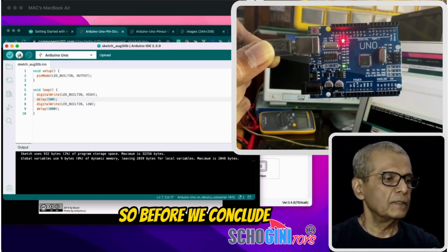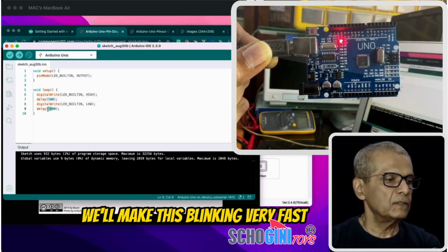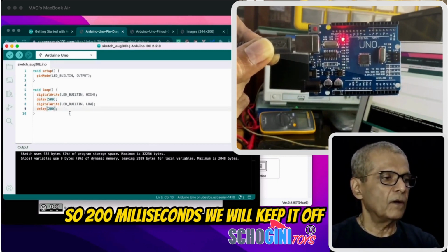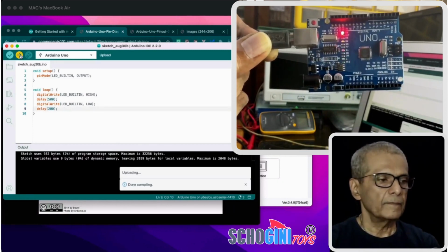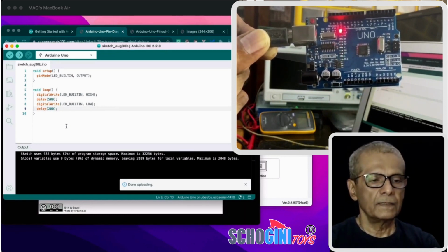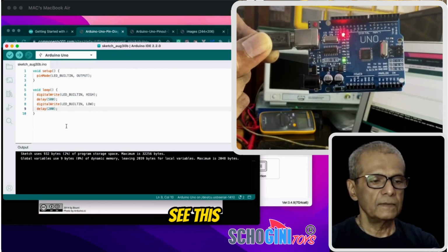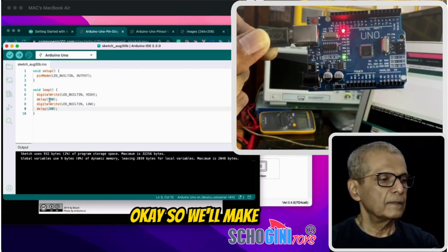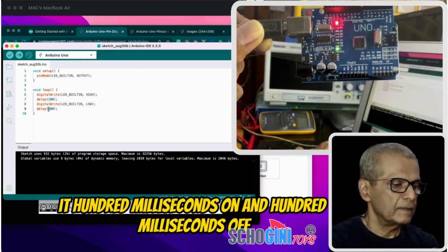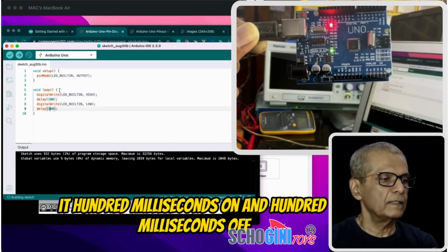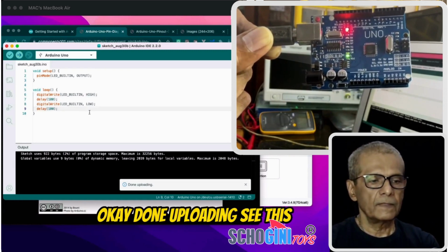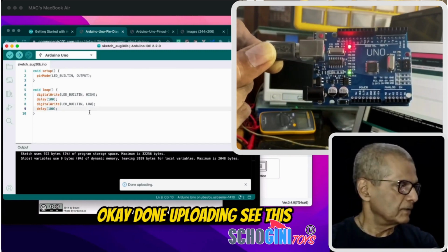Perfect. So before we conclude, we'll make this blinking very fast. So 200 milliseconds, we'll keep it off. Done compiling. See this? Okay, so we'll make it 100 milliseconds on and 100 milliseconds off. Okay, done uploading. See this?